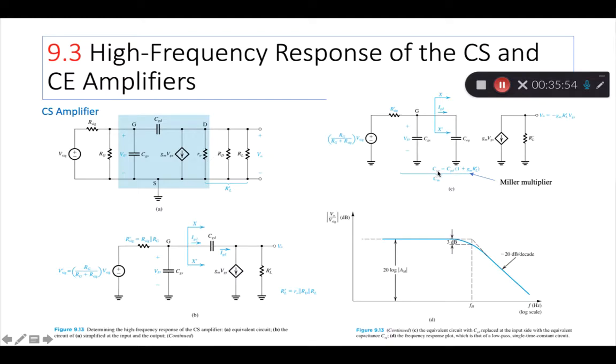So it's almost like this C equivalent is the original capacitance multiplied by some number, 10, 50, whatever. Then the two of them are in parallel, so together they give you C. And you know, parallel capacitors, you just add them, right, to get the equivalent value. So that is a simplified model.